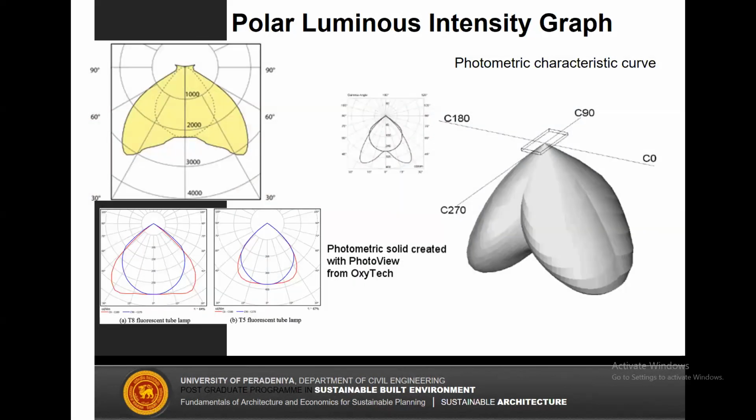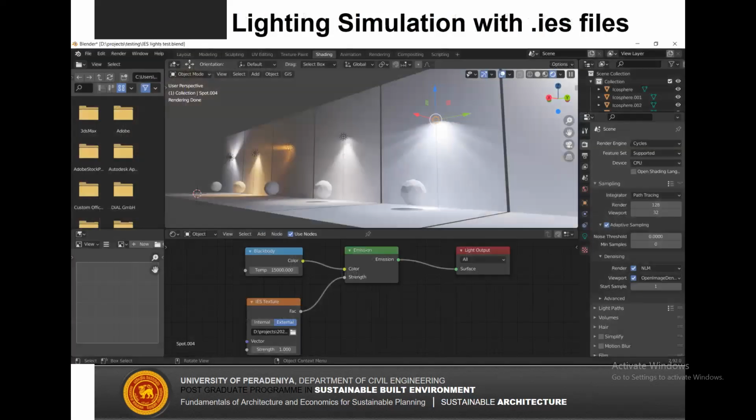And actually, this is also not important these days. Right now, when we select light fittings for interior lighting, we ask the lighting manufacturer to give us the .ies file. IES stands for Illumination Engineers Society, I suppose. So there's a file called .ies, which gives the light intensity distribution of the light fitting they have created.